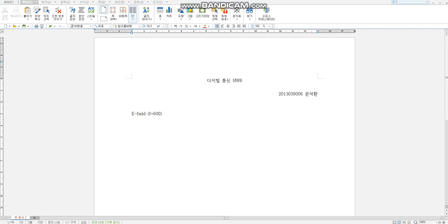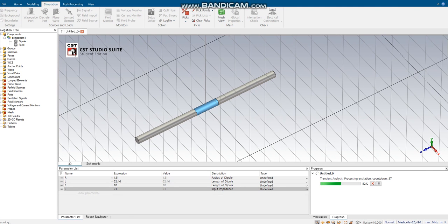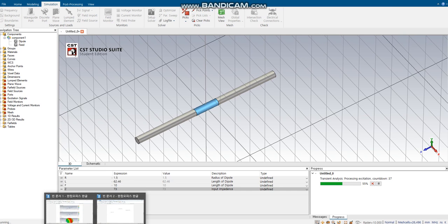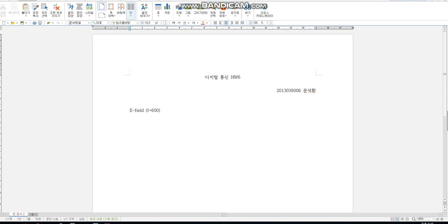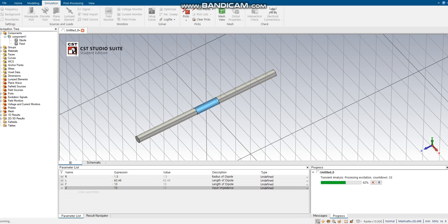So then we got the values of the parameters here: the width is this one, fi is this one, WF, which is the width of the feed line, is 2.92, gap is usually 1, and this one is the formula I got from the book. Lg is 2 multiplied by L, Wg is 2 multiplied by width, and this is Ht, and this is Hs, and this is the outline we just drew to make it easier and more comfortable for ourselves.